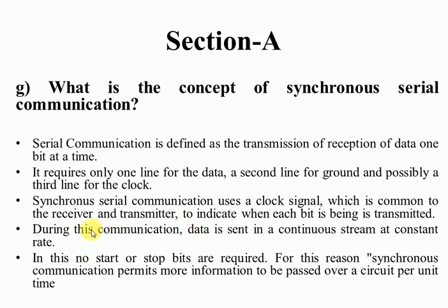In this no start or stop bits are required, so we can say that more information is shared, because we are not sending any start or stop bit; we are sending only those bits which are required. After that we are not sending anything. To know whether a bit is transmitted or received, we have the clock signal. So hopefully you have got the concept of synchronous serial communication.